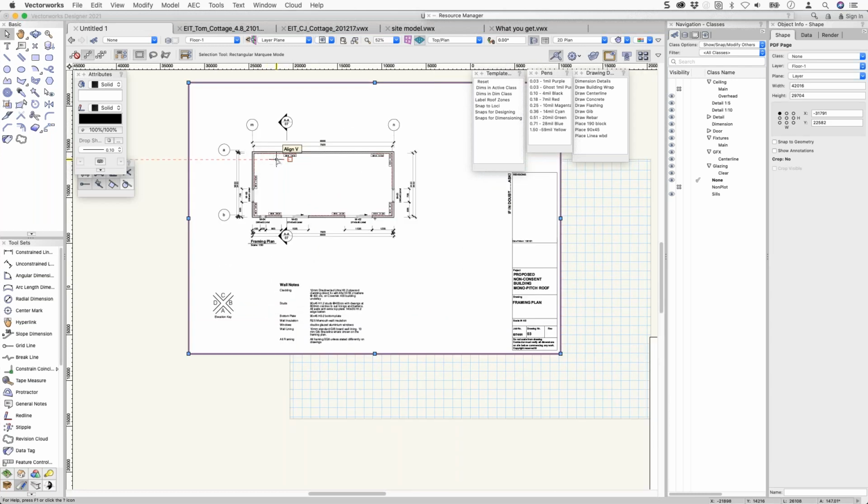But one of the first things I want to talk about was the difference in PDFs. If I import a PDF that's been created from a scanner, so you've scanned blueprints and brought them into Vectorworks, you can't do the next trick that I'm going to do, which is to snap to geometry. There are 2 sorts of PDF files. One's called a raster PDF file, which is nothing more than a bitmap or a series of dots on the screen.